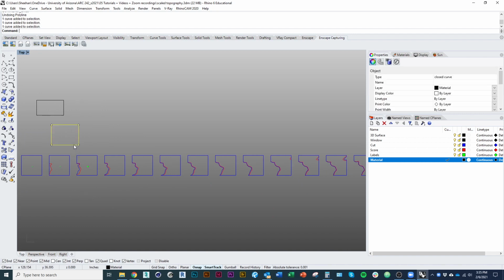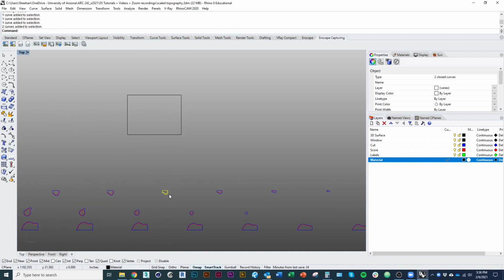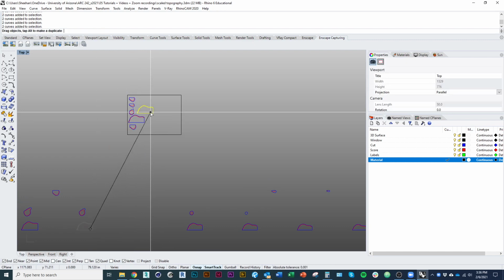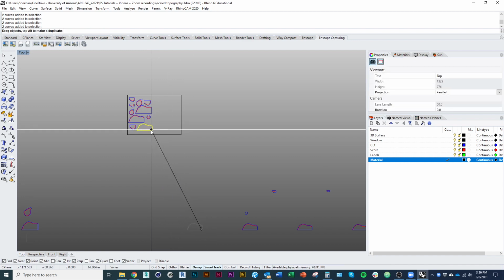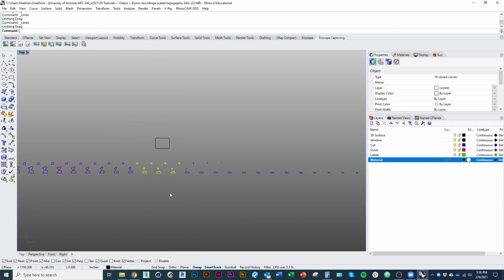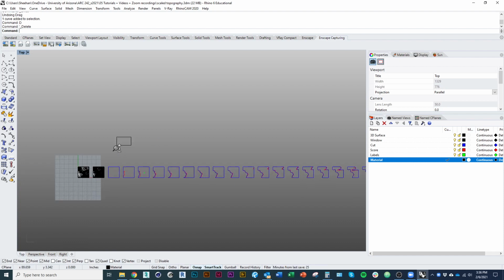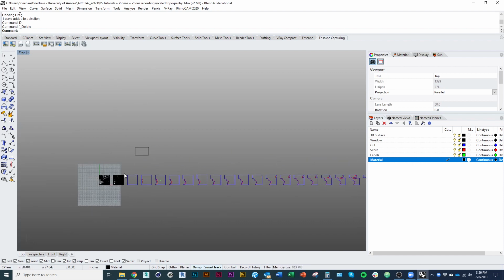And then once I get further down the line and I'm cutting some of these smaller pieces, and again, I've already got them all individually labeled, so I can keep track of them once I cut them. I'm putting a bunch of pieces into one layer. You can spend as much or as little time as you want nesting your cut pieces onto a sheet. This step will not be required as part of your submission, so you can leave your file laid out just like that. But anyway, then you would start to create independent sheets and lay all your pieces out onto those sheets. Figure out how many sheets you need, cut them all to the right sizes, and get all that stuff ready before you go down to your laser cutter appointment and start making this model.